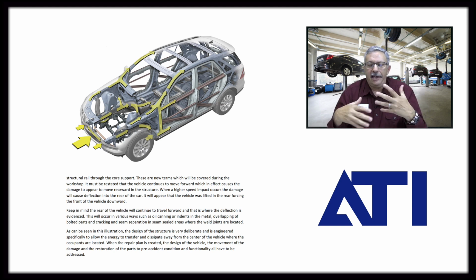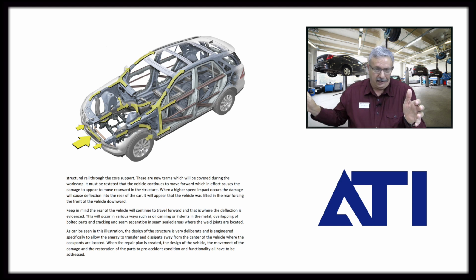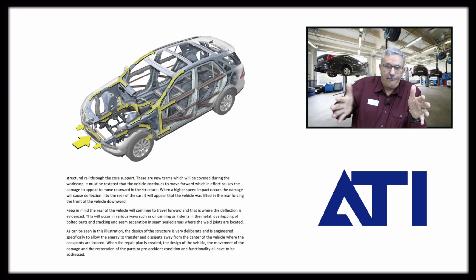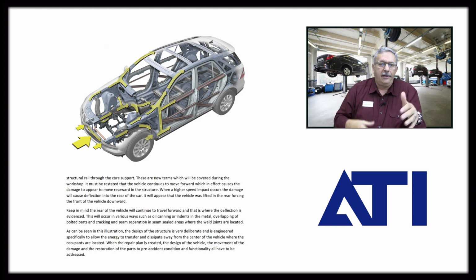So again, we're going to cover a lot more of these things in greater detail, but it's really important to have a firm understanding that the damage just doesn't stop in the area of direct damage. It's going to continue going till it loses its energy. And we've got to remember, where it lost its energy is the first place you've got to check for damage, so that I can pull that damage back out in a way that will restore the structural integrity back to the vehicle.